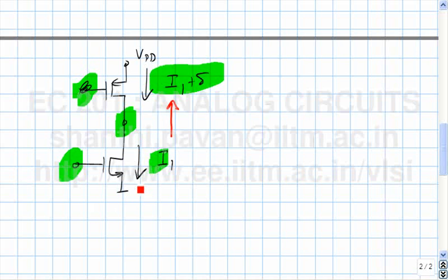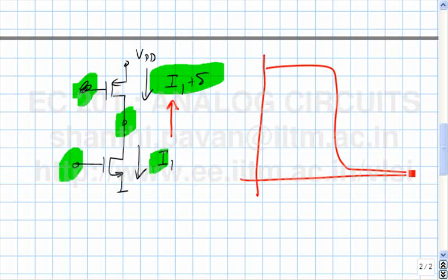Okay? So when you have a very high gain amplifier like this, you will get the high gain only when you are biased in precisely this small window. Even a small change in the input bias voltage will cause you to be either operating in this region or in this region. Does that make sense? And this is fundamentally true for all high gain characteristics. It's nothing special with the MOSFET or whatever this is.